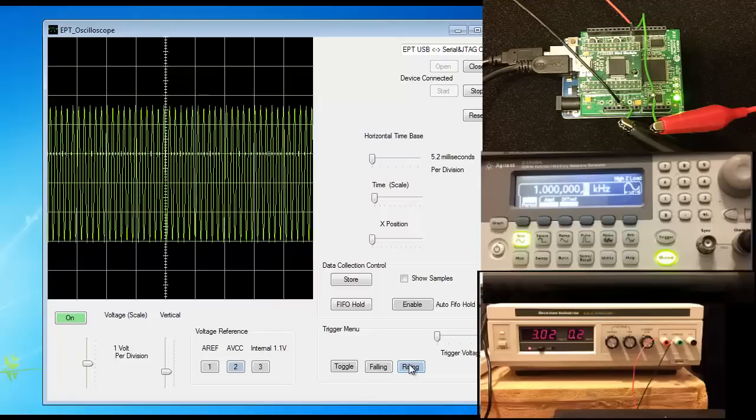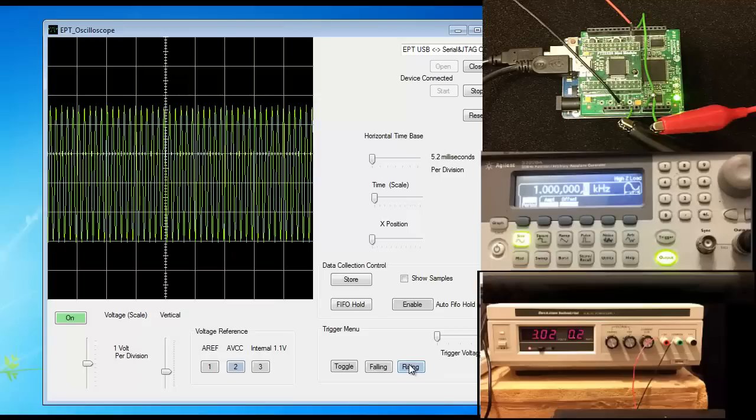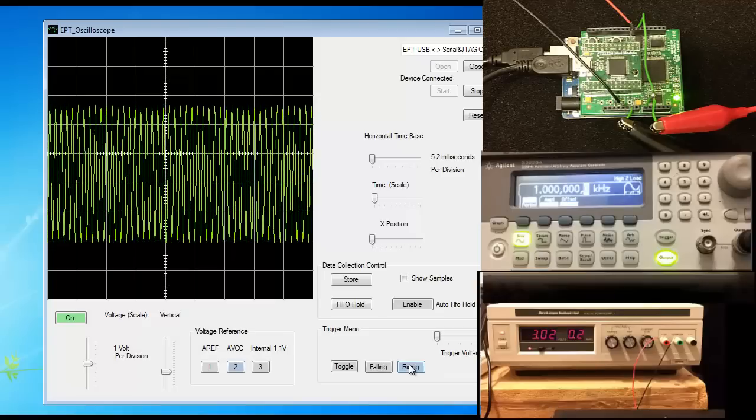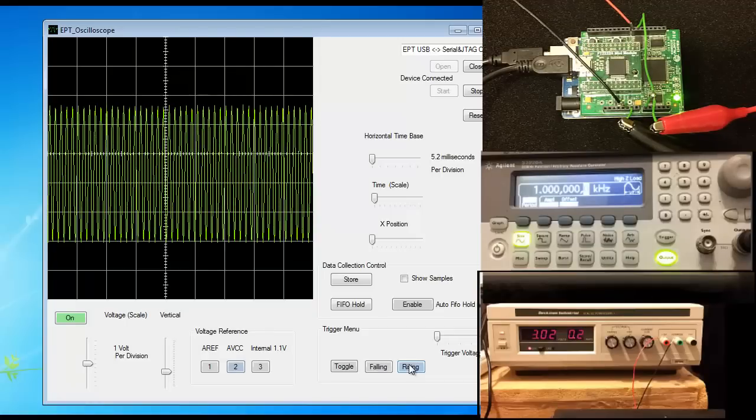The fast Arduino scope does have its limitations. It is most notably limited by the ATmega 328 microcontroller. The chip uses an ADC, which we select the 8-bit mode to increase the throughput speed.